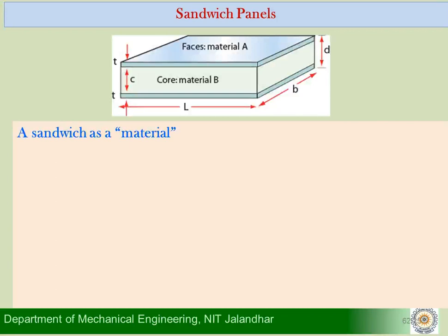Now we have also seen earlier that we have been representing shaped materials as a different material itself, although we have known already that by shaping steel you do not create a new material, or by shaping aluminium with a shape factor of maybe 30-40 you do not create a new material, but it's a pseudo material which has properties which do not match those of the base aluminium with a shape factor of 1. That is why we say hypothetically it is a new material.